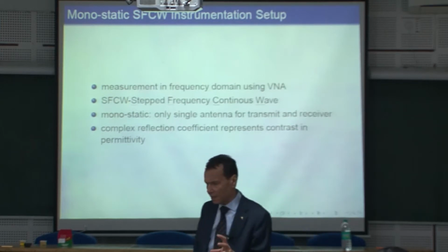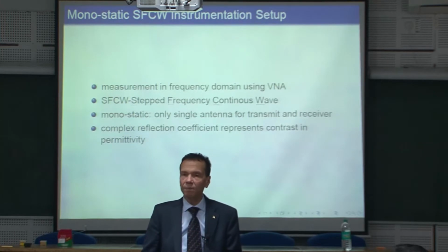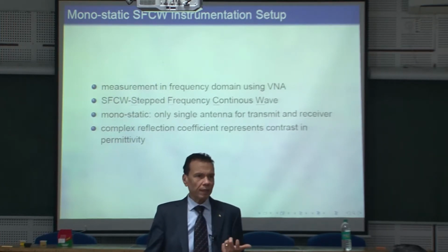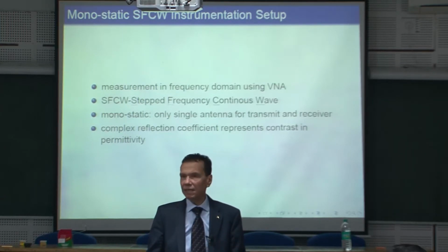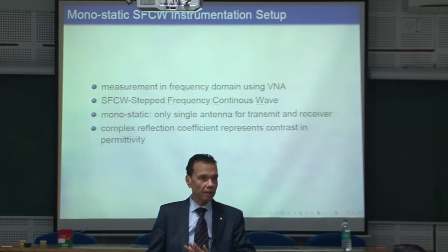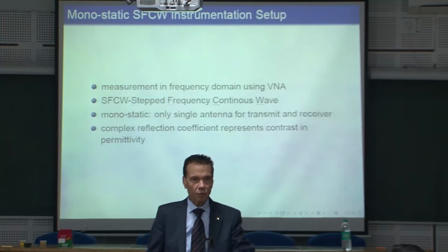Let me tell you something about that. In order to illuminate or to excite the system, you have different ways. What we discussed before is stepped frequency, which means I will switch on my generator. I will generate a monochromatic signal. I will wait until all transients die out and the system settles down, and I measure the steady state response. Okay? When I'm done and I measure the steady state, I switch it off at this frequency and switch on the next frequency. Therefore, it's stepped frequency.